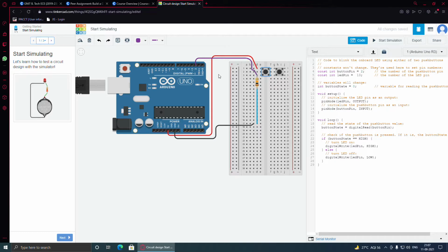So what will happen, in order to obey Ohm's law, that is V is equal to IR, the current I will increase exponentially, because the voltage is quite high, 5 volt, and the internal resistance will be very low, a few milliohms or lesser than that. So the current will be very high, so much so that it will kill the component within a short time, if not instantly.